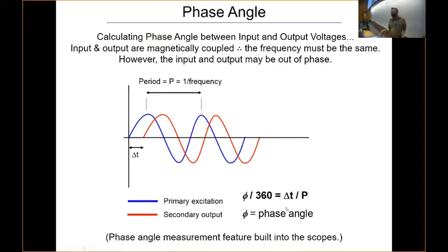Now, you're going to be using an oscilloscope for this lab. Part of this lab is just becoming more familiar with an oscilloscope. You probably used one in circuits. Fortunately, we have some really nice new oscilloscopes in lab now. There are a couple different ways of measuring it. There's a cursor function. You can set a cursor here and then set the other cursor here, and it will tell you the change in time between them.